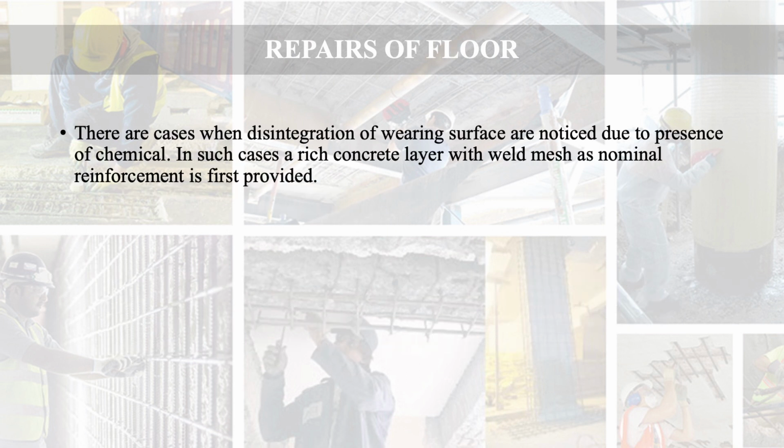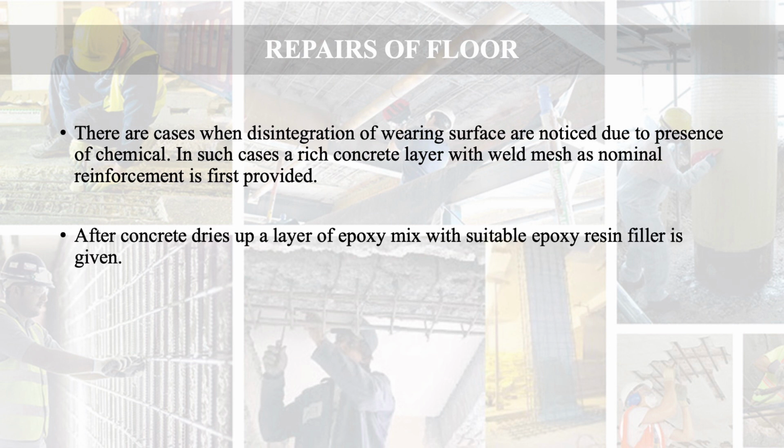There are cases when disintegration of wearing surface is noticed due to presence of chemical. In such cases, a rich concrete layer with weld mesh as nominal reinforcement is first provided. After concrete dries up, a layer of epoxy mixed with suitable epoxy resin filler is given.